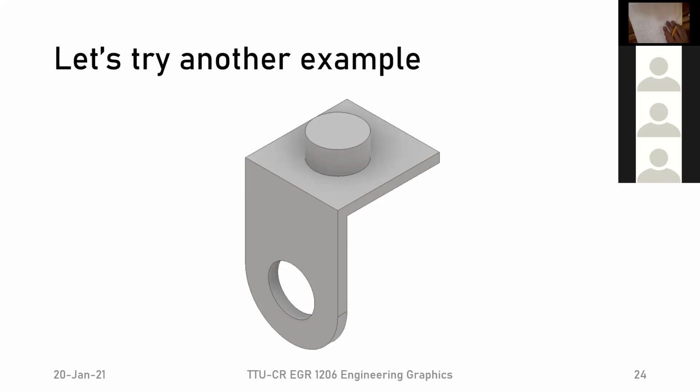All right. Okay, so now let's not forget the hidden lines for the circle, though. All we have to do is find where the top of the circle is. Our top of the circle is here, and so we can just go across and do our hidden lines. Sometimes with these thinner ones, as I said, these hidden lines can be a little tricky because there's not that much place to do dashes. So these would be our hidden lines. Now we have all our hidden lines and all of our visible lines. So what's left is to draw our center lines.